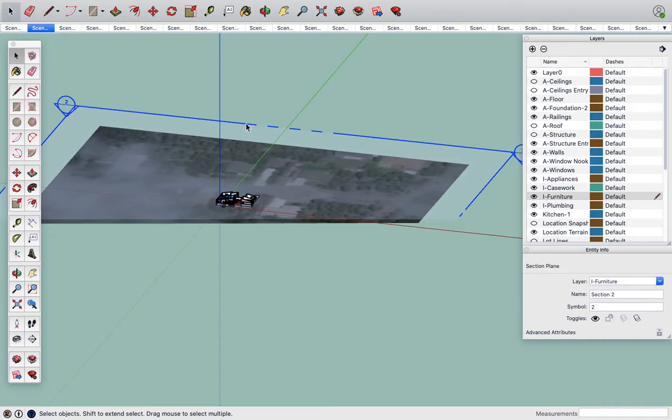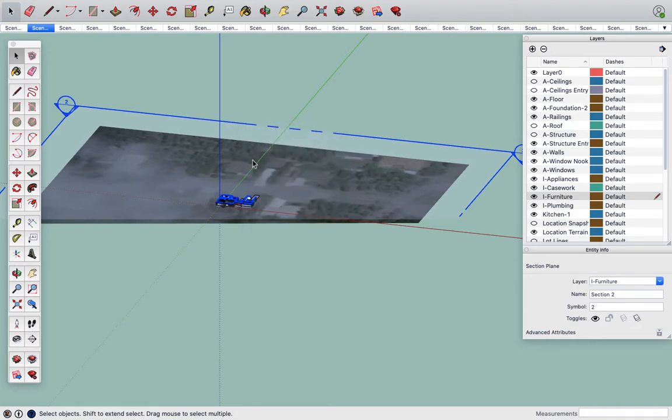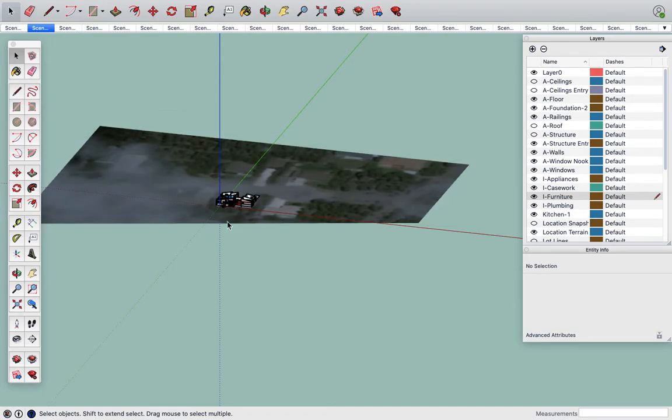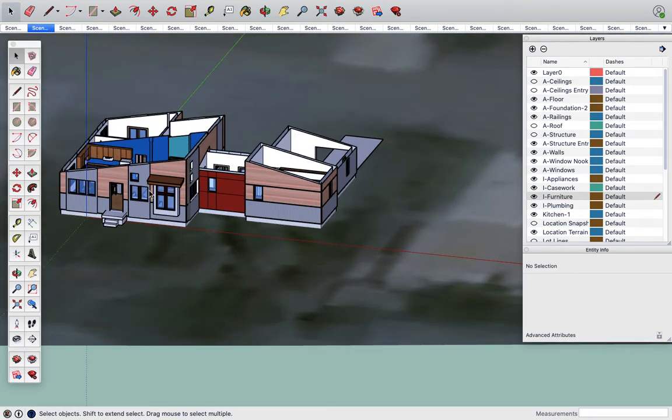So usually I just click on it, right click, and I guess I can't right click and delete it. So I'm gonna just click on it and delete it. Because now I want to show you how to do a vertical cut, which is a really cool view called a section. So again, pick a vertical plane. I'm going to slice this way through my building, and I'm going to hold down shift just so it doesn't jump around as I go to the side of my building.